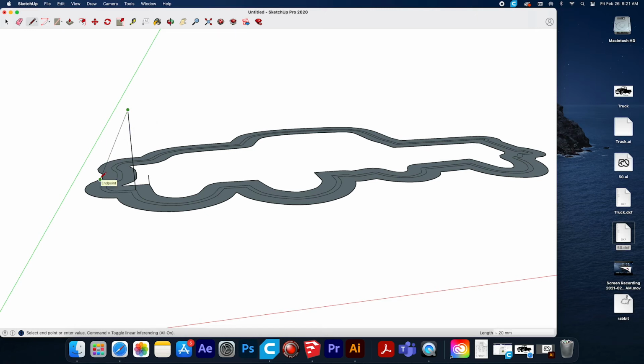And then this here, I'm also going to do blue axis, but I'm going to type 16. And then somewhere on the outside, and so this is basically my height for the cutter. This is my height for the base. So I can do another height for the base here. I'm just holding that. I just sort of drifted that up, and there's no clicking or anything after I've got that one point in. I just drift the mouse up and make sure I'm on the blue axis.